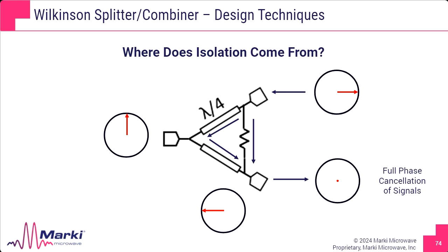So we have quarter wave transformer sections, only now it's sectioned up as you go through the divider, where each one is creating an isolation null at different frequencies. So you have these designed for isolation at different frequencies across a given bandwidth. And then it's simply connected together. So it looks kind of like this, and then another one. And each one of these is going to be another resistor and another resistor. And of course, it's the same over there.